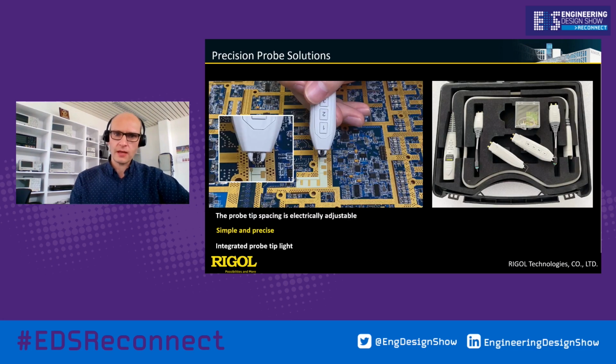With that one, we have different probe heads inside. So for example, when you decide for such kind of probe, you have probe heads for the differential testing, you have probe heads for the single-ended testing. And for the single-ended connection, you have also 3 different kinds of hot pins and 3 different kinds of ground connection capabilities. You can replace this by your own, and the box with the replacement pins is available in this probe set. And we have as well probe heads for soldering.